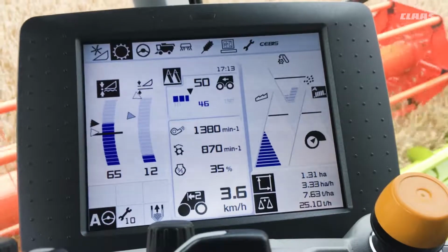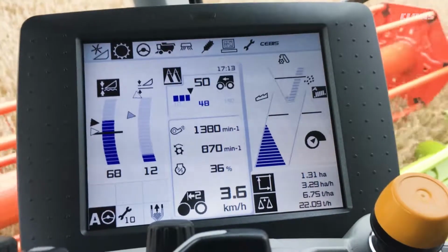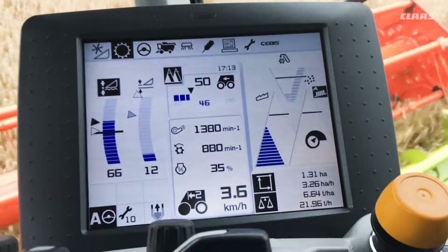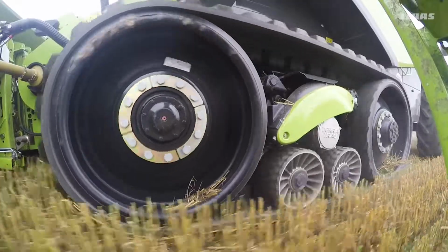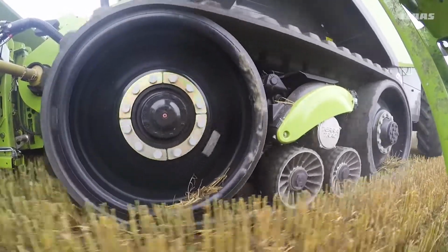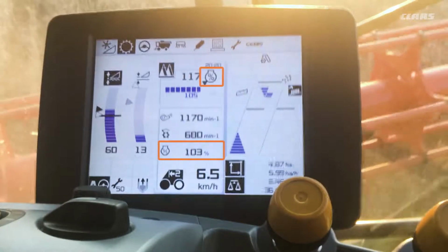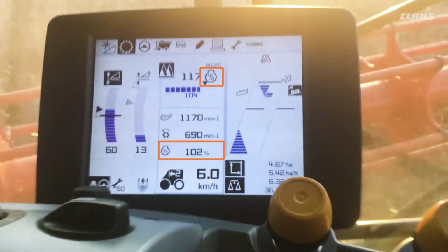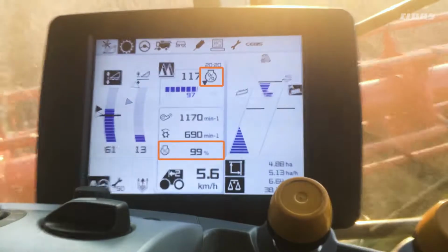As you would expect, Cruise Pilot may well switch back and forth between two or more limits, depending on which factor has the strongest limiting influence at that moment. If the engine load exceeds the maximum engine load set by us in the main menu, the ground speed is limited, or even reduced if necessary. The engine symbol is displayed to show us that this is happening.